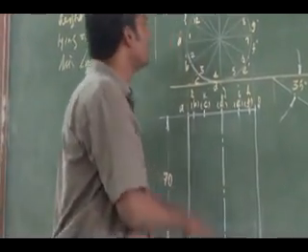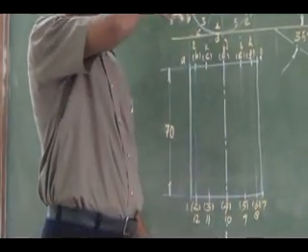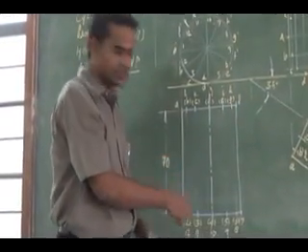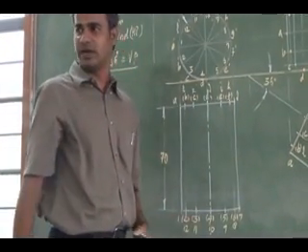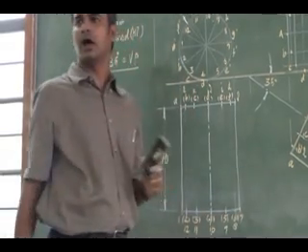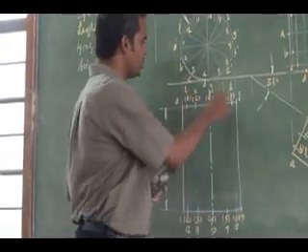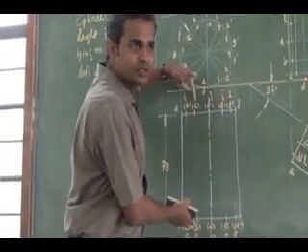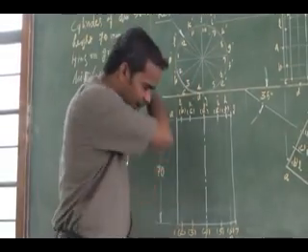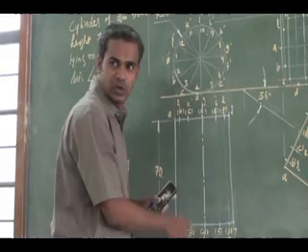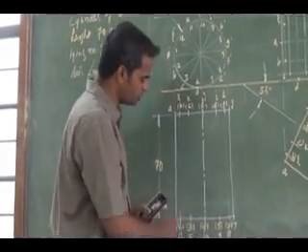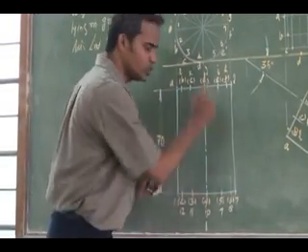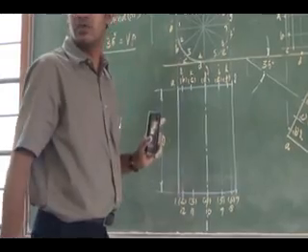Then you divide the circle into 12 segments, and all the points of both the bases have to be marked carefully in the top view. The hidden base circumference points should also be marked with brackets. This top view is for 35 degrees. I haven't shown the generators in the top view. The generators are projected only to mark the base corners. The generators should not be visible.